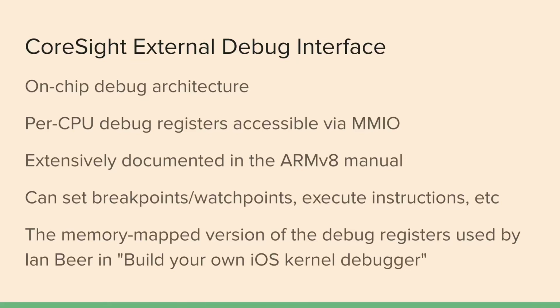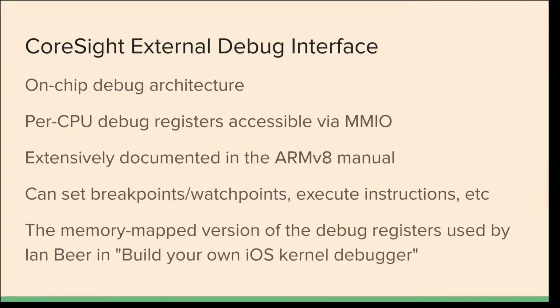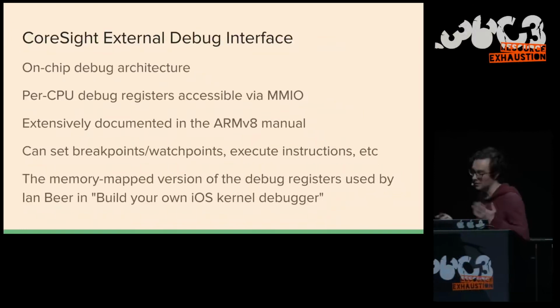But what I will say is that the external debug interface is certainly more than powerful enough to do any sort of kernel debugging that we might be interested in. It's definitely capable of setting breakpoints and watchpoints, single-stepping execution, executing arbitrary instructions, poking at memory, all this sort of stuff.